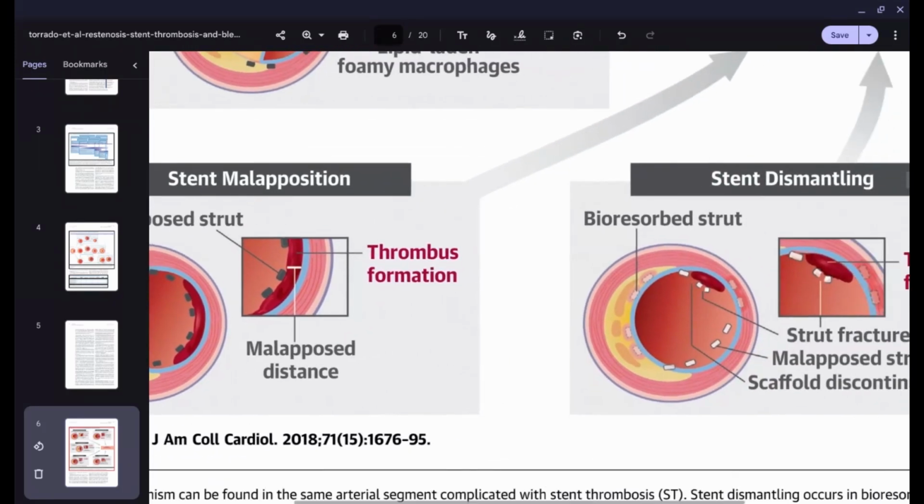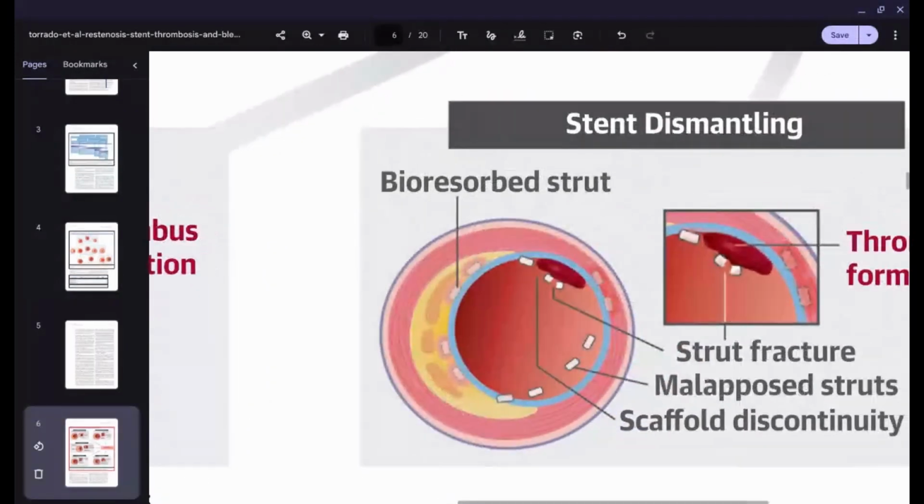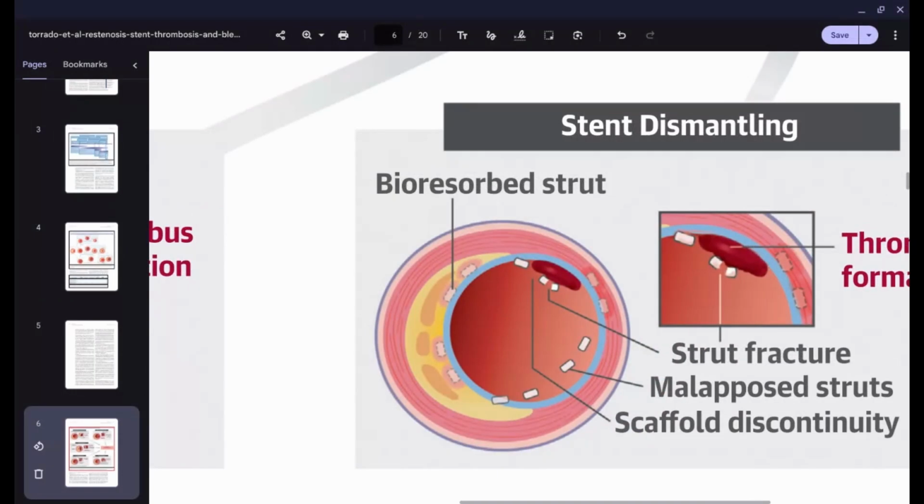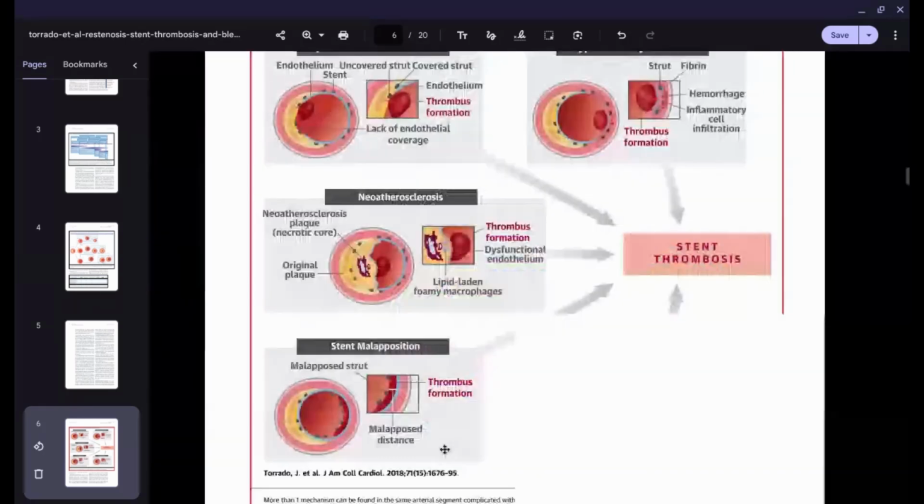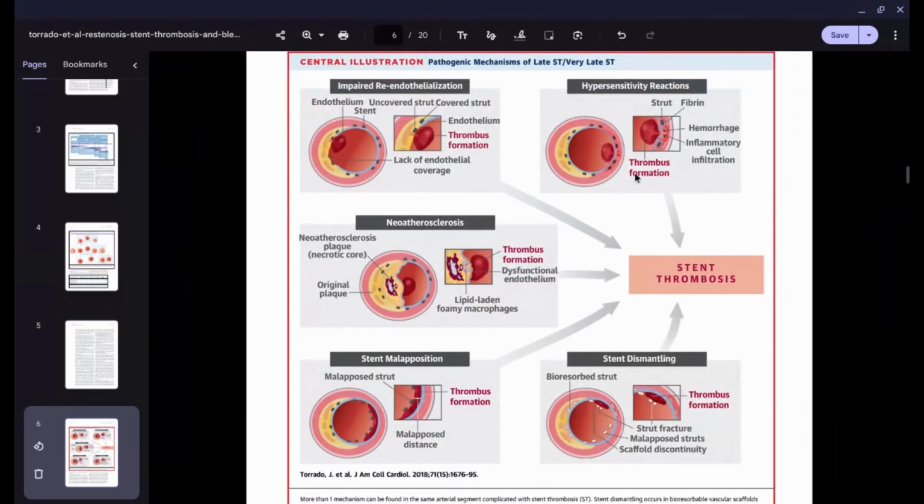Sometimes what happens is the stent tube that you put in fails. We already discussed fatigue, and that is an important criterion, right? If the material is not good, the stent simply breaks apart. Or in fact, you designed it to be bioresorbable, and there is a part that is still hanging in the lumen, and that fails. That failure typically damages the endothelium and leads to clotting. So there are at least 5 typical paths. All of them lead to stent thrombosis.